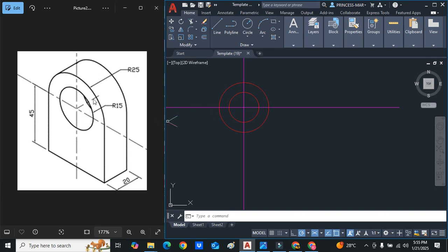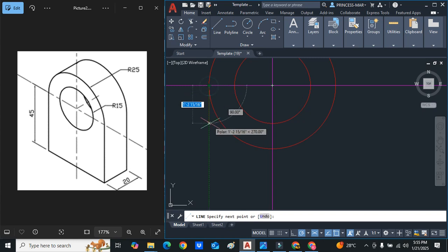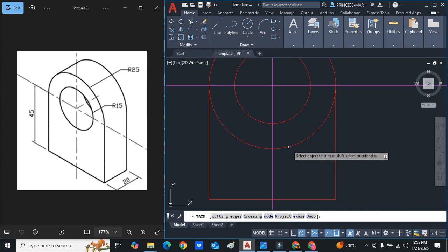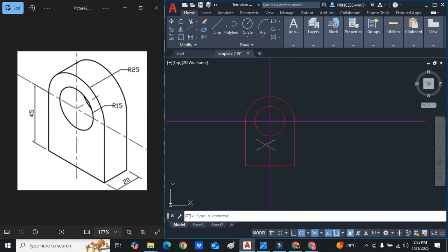And you would realize that that 25 touches the right side, it touches the left side. So that is the length of this view. We just need to bring those edges downwards to 45 down. So we come down 45, we just draw this line across, long, no measurement. And then we just project down this left side, and that's the length of the figure. So this front view is finished.